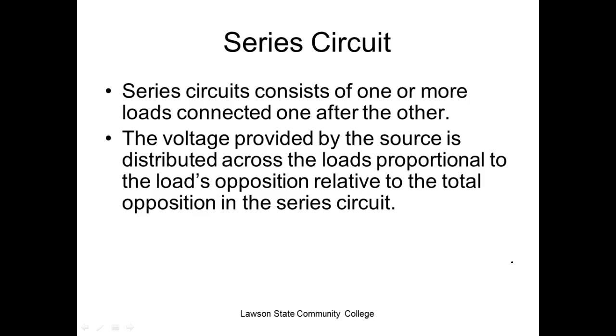So what advantage do series circuits have? Well, series circuits allow us to use loads that are rated at lower voltage, because the voltage is divided out. So now I can have my Christmas tree lights and use these little tiny lights, right? They're not rated at 120 volts. They're usually rated about 2 volts, or maybe 4 volts. If I can put so many of them in series, and they all have the same resistance, then you can hook them up to 120 volts and still not mess them up.